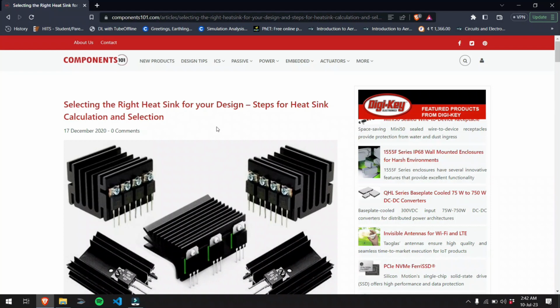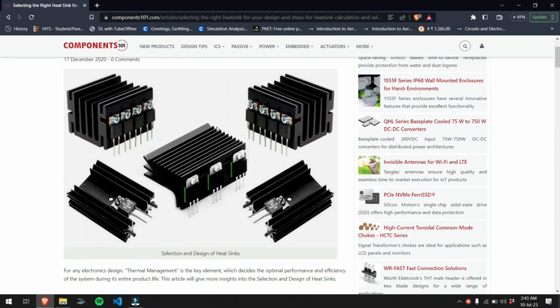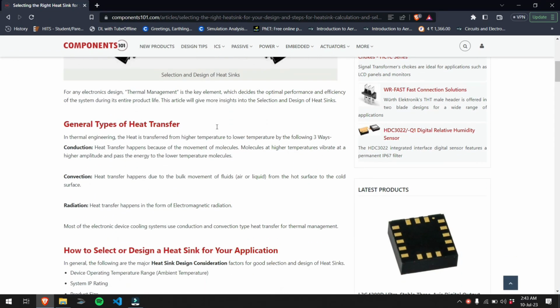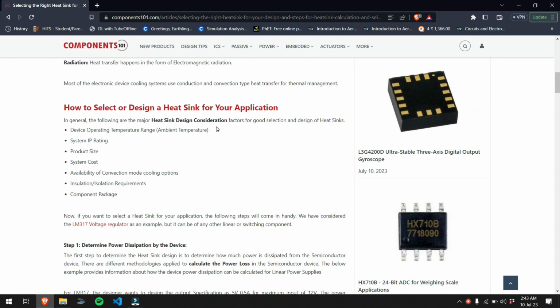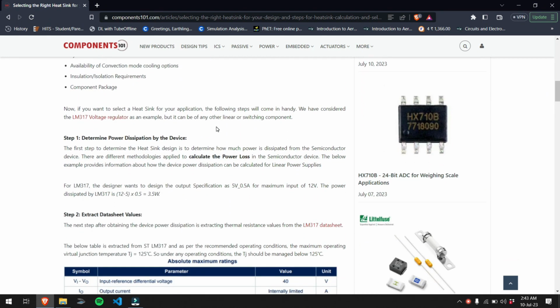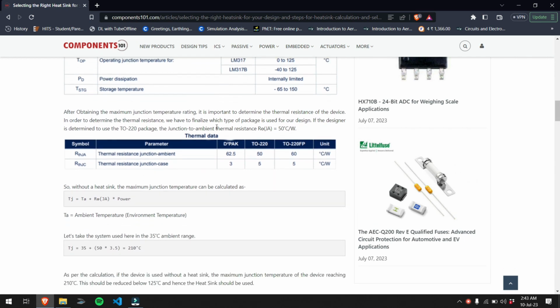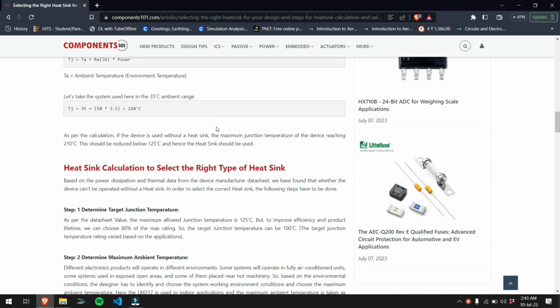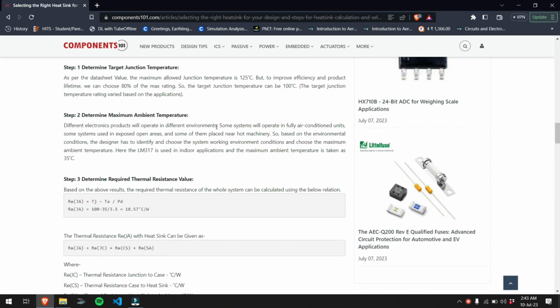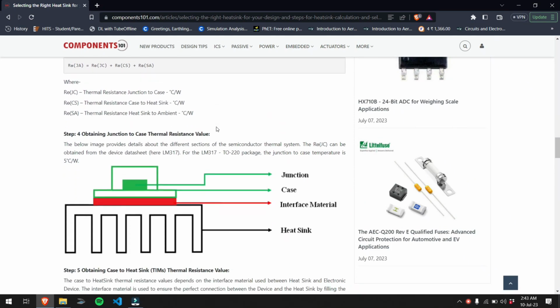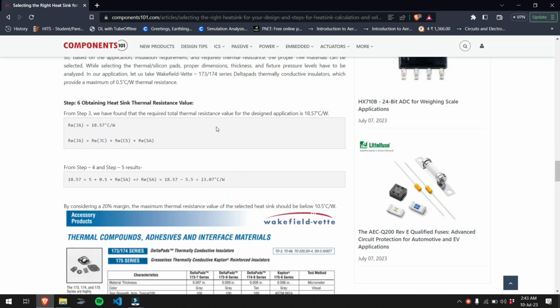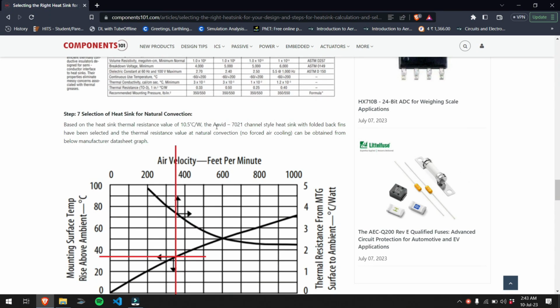For those of you looking for a more detailed exploration, we've got just the resource for you. This site offers an in-depth guide to choosing the ideal heatsink. It covers topics like thermal resistance and capacity and highlights the need to consider factors like ambient temperature, power dissipation, and allowable temperature rise. You'll also learn about different heatsink materials, thermal conductivities, and the use of thermal compounds to enhance heat transfer. Choosing the correct cooling solution could vastly influence your outcomes.